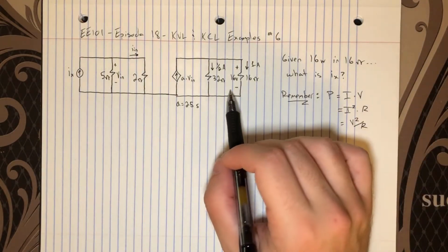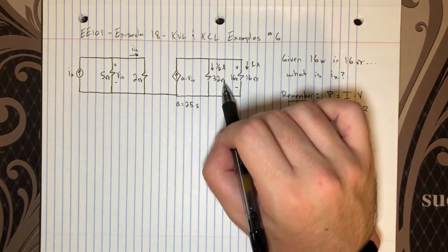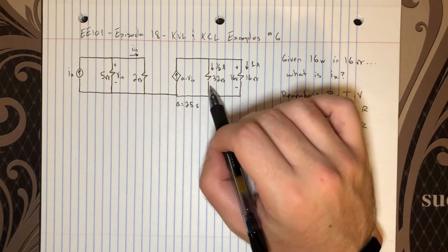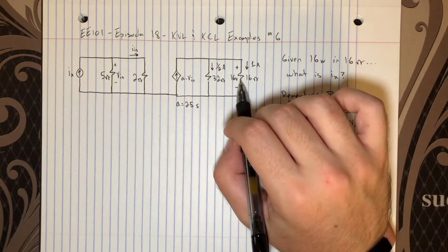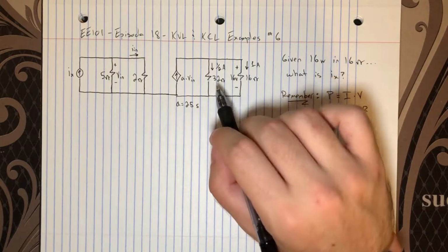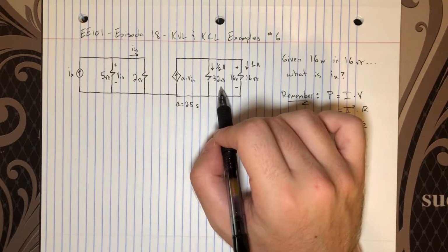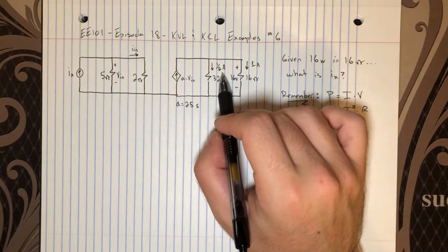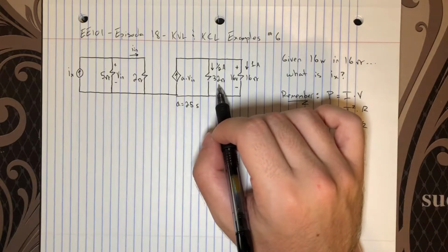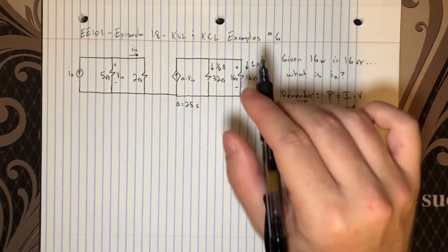And this is also interesting. I like this example. I didn't plan on this, but this is a good point. Notice that the voltage across these two resistors is the same, but one resistor is double the resistance of the other, and it just so happens that the resistor of double the resistance is carrying half the current. I know I didn't explain that, and it's just a consequence of the algebra, but it also has physical significance,